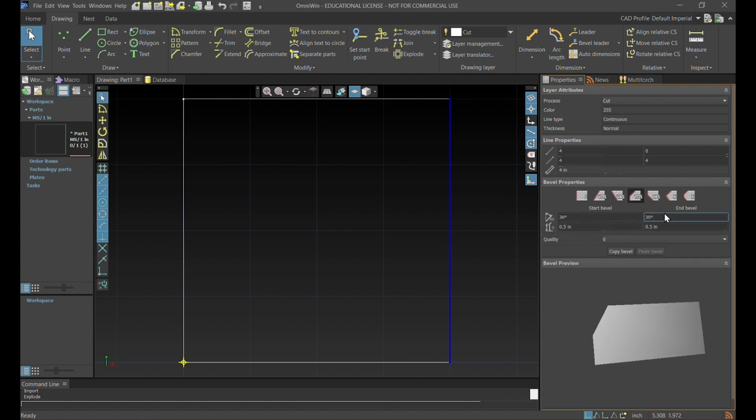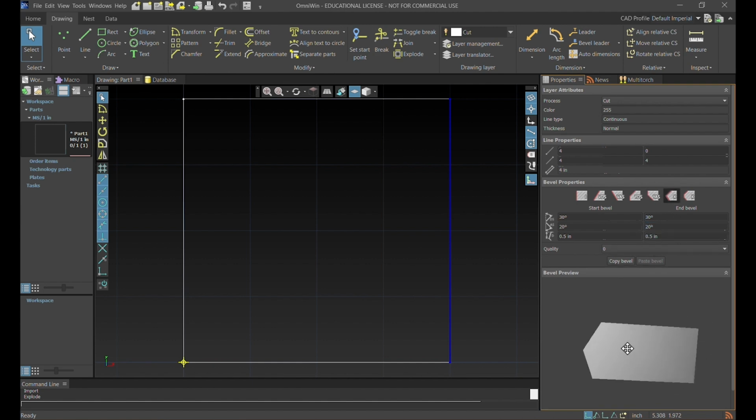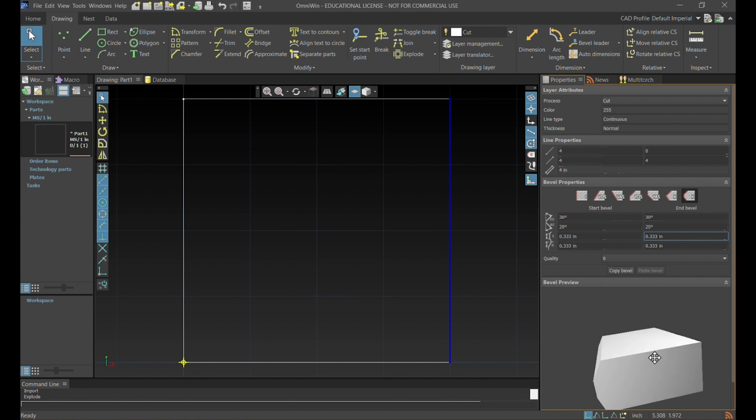YDS and YAS, which consist of an I cut and a D or an A bevel cut. X, which is both a D and A cut that intersect. And K, that is an I cut along with both a D and an A cut.